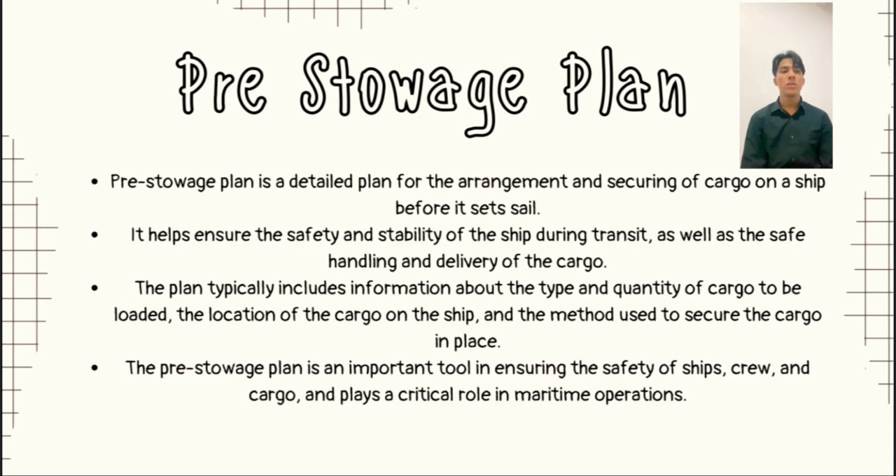On the other hand, the pre-stowage plan is the initial step of the cargo storage plan, which takes into account pertinent information about the cargo that has to be loaded into the vessel. The type of cargo, its weight and size, and any specific handling needs are all included in this information. The pre-stowage plan also takes into account the stability and capacity of the ship, as well as the positioning of existing cargo. By considering the center of gravity and stability of the vessel, this plan aids in determining the most effective and secure method of loading the cargo and guarantees compliance with all applicable safety rules.